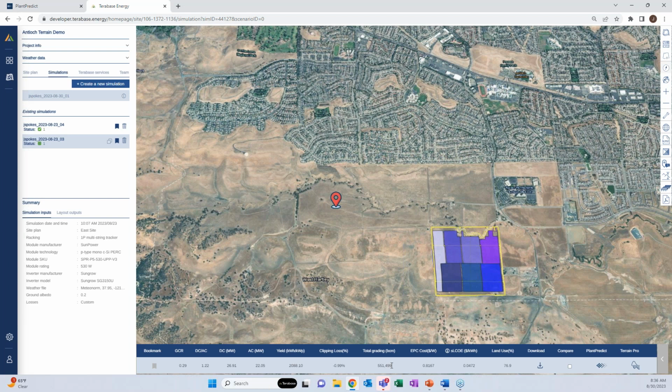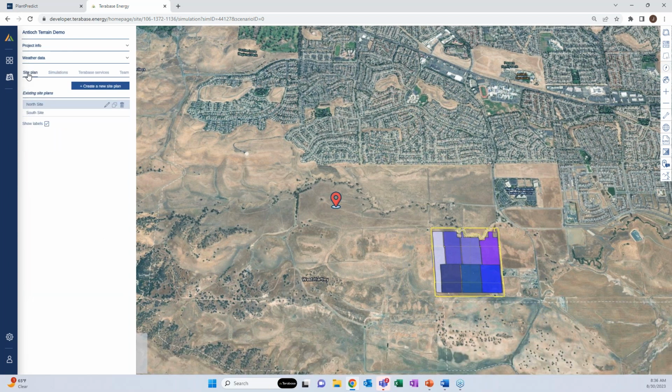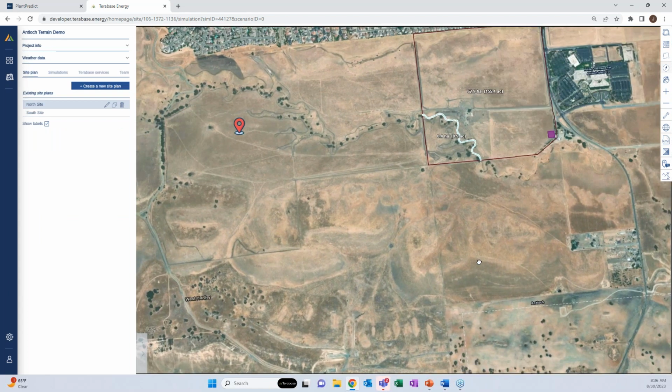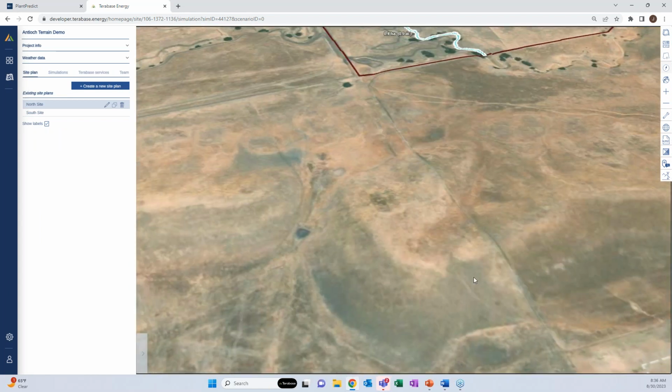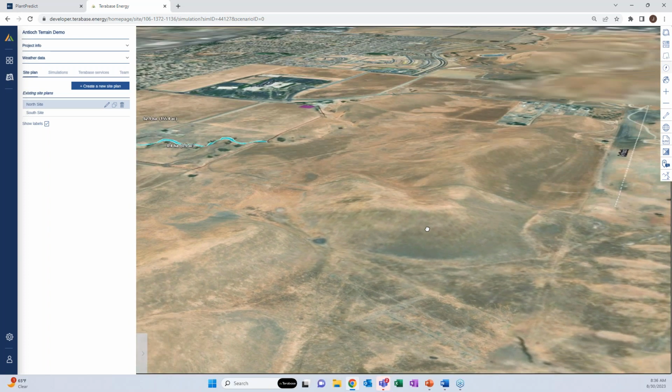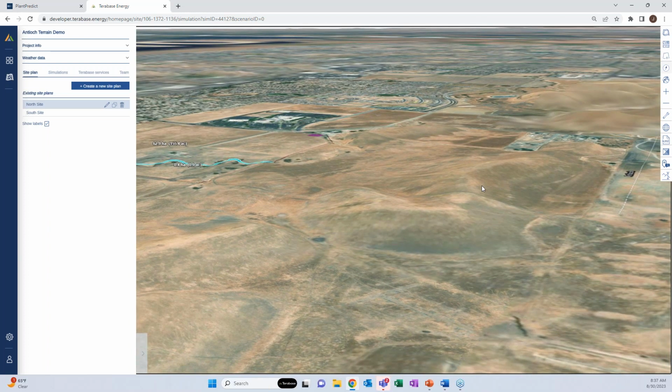So there's a huge difference, a nearly 5x difference in those earthwork quantities. And so if I take a quick look at going back to my site plans, and I look at these sites from a 3-dimensional perspective, I can definitely start to see that my south site has much more terrain than my north site does. And so that's coming through in our earthwork quantities estimate.